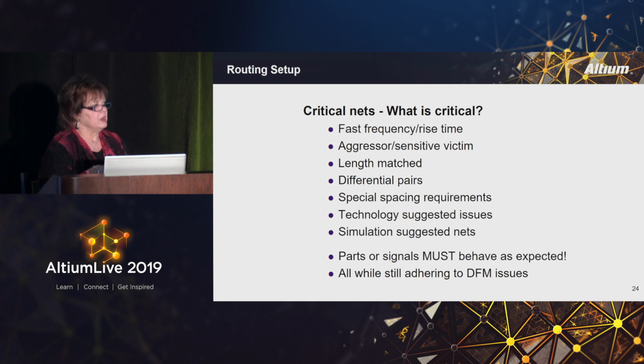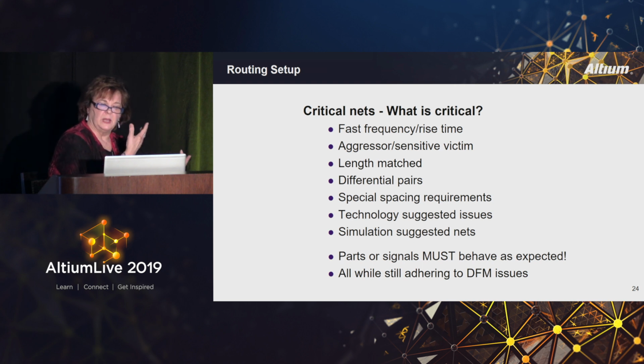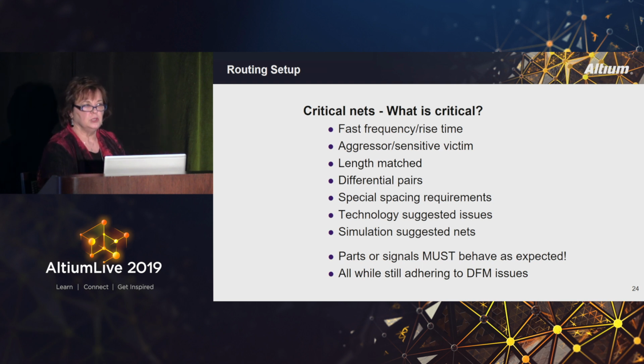And so all of the things that you do because they're critical, you're going to want to pay special attention to them, and you're going to want to have them on the inside of the board, in internal layers as opposed to external layers, because of the reasons I talked about a minute ago. It's just not easy to control things on the external layers. And you need to do all of that while you're still adhering to all the DFM rules that your manufacturer needs. And if you don't know what the DFM rules are because you haven't been exposed to them yet, then